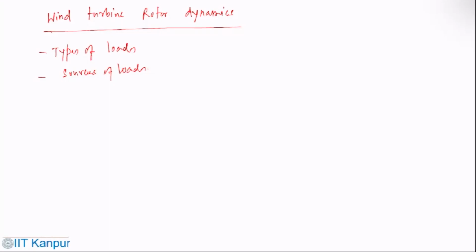Then gravity is there, which could be a source of loads on the blades for large turbines, although it is less for smaller machines. Then you can have dynamic interactions, where motion induced by aerodynamic and gravitational forces in turn can induce loads in other parts of the machine.